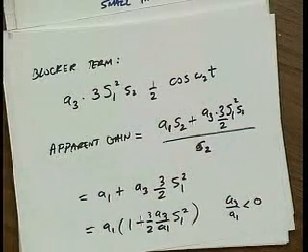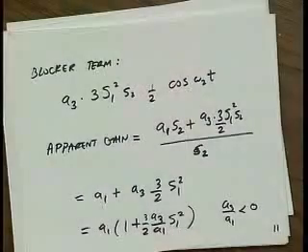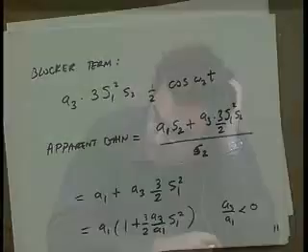Yes? So when we put an SNR, we do the signal in-band to the noise in-band, right? Obviously, any out-of-band signal will be IM3 interference into in-band. So when we calculate noise, we have to integrate over the whole spectrum. Okay. You brought up several concepts. Let's keep the discussion simple. Let's not talk about noise. Let's just talk about distortion.